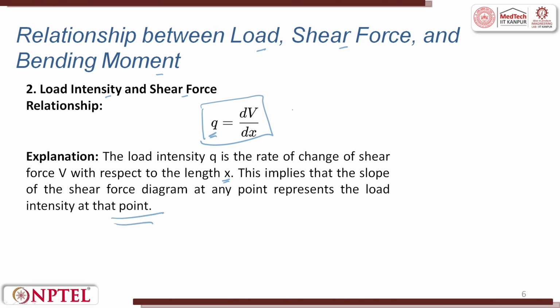So it is very clear there is a relationship between shear force and bending moment: V = dM/dx, the rate of change of moment with respect to x gives the shear force. Now, between load and shear force, the change of shear force V with respect to x gives the load intensity at a point.